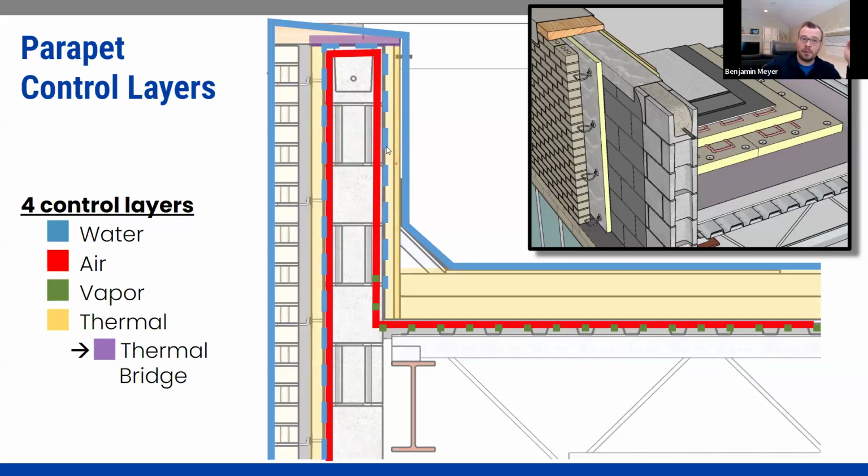The taller this parapet wall gets, the more challenging this would be, the more you might want to look at essentially doing some vermiculite filled cores for a few courses and making that separation there versus having lots and lots of insulation, not really conditioning the interior space. As that wall gets taller, it's not really part of the interior space.